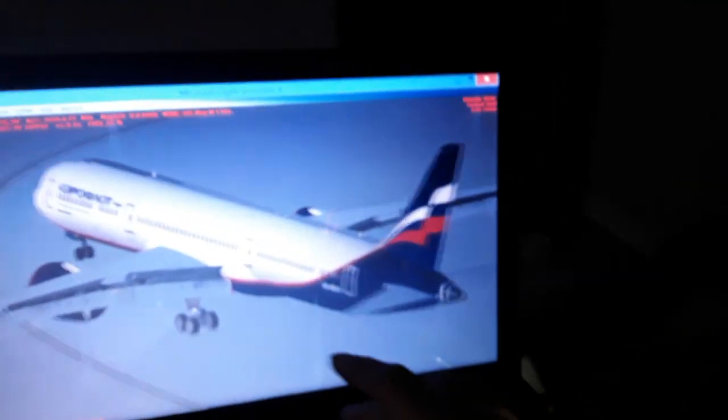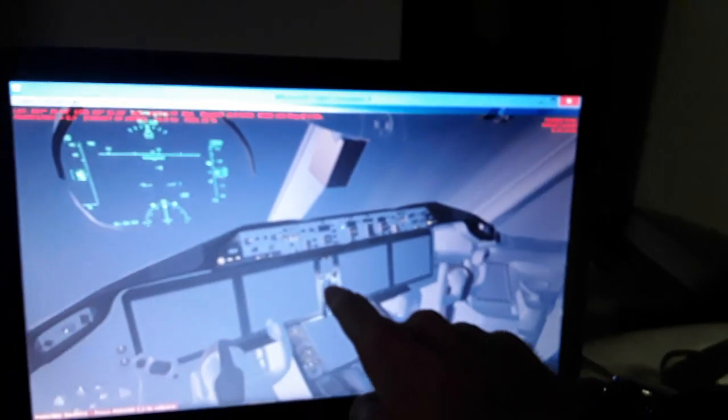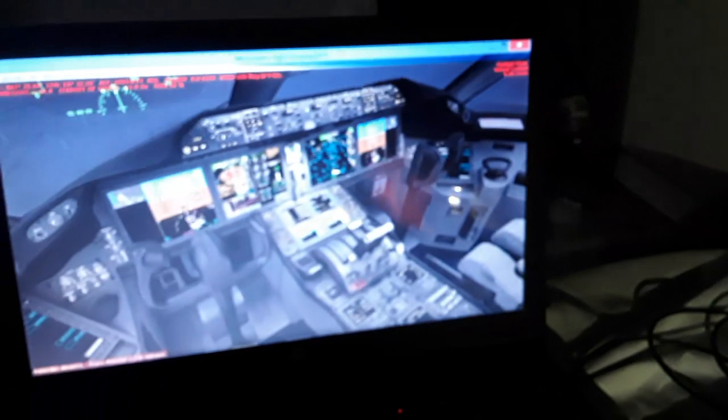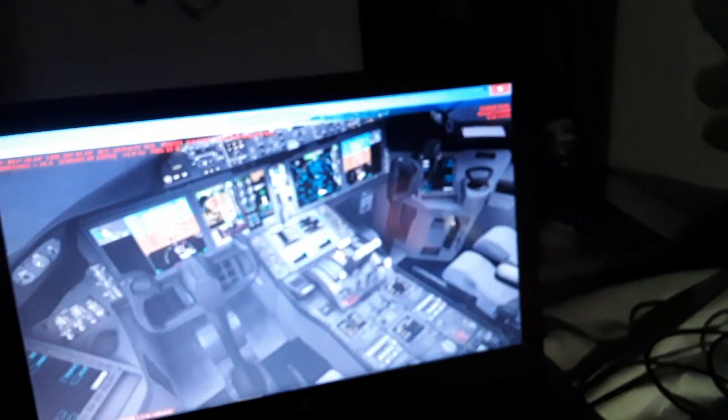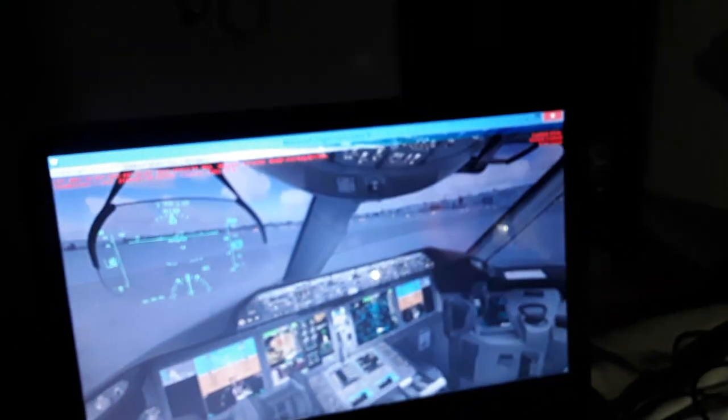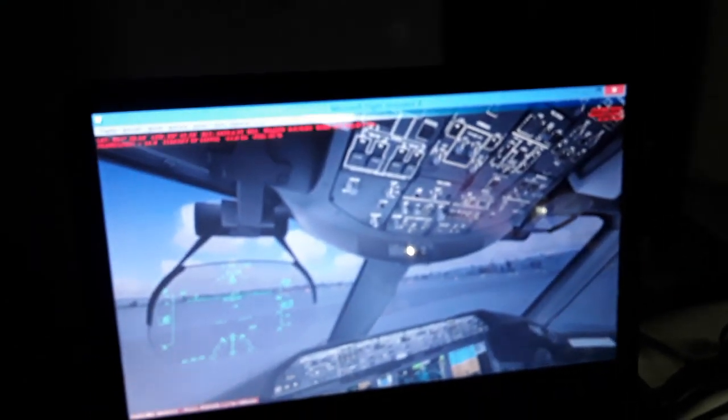Also the landing gear extend and retract needs hydraulic pressure, rudder pedals, all flight controls, nose steering, thrust reversers for the engine, flaps, speed brakes, parking brakes. So you see the flight controls move with hydraulic power from the engines.